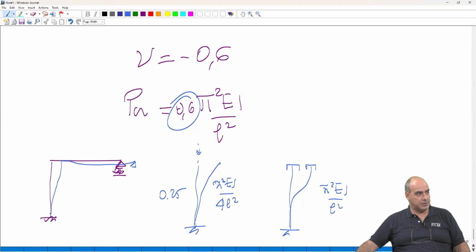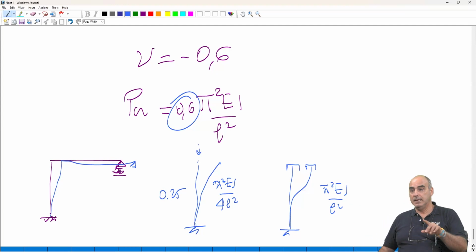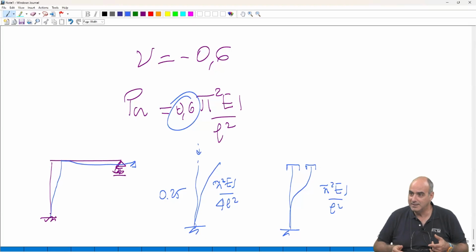Go for dry connections, okay? One thing, dry connection is post-installed in most of the cases. It's post-installed on some pre-installed fixtures. So your carpentry must take into account the tolerances. You cannot risk to arrive and have a hole which does not match. Your hole will never be circular, it will be a slot to accommodate that, because you cannot risk to arrive there and wonder, where shall I put my reinforcement? You don't see the hole when you look into that.